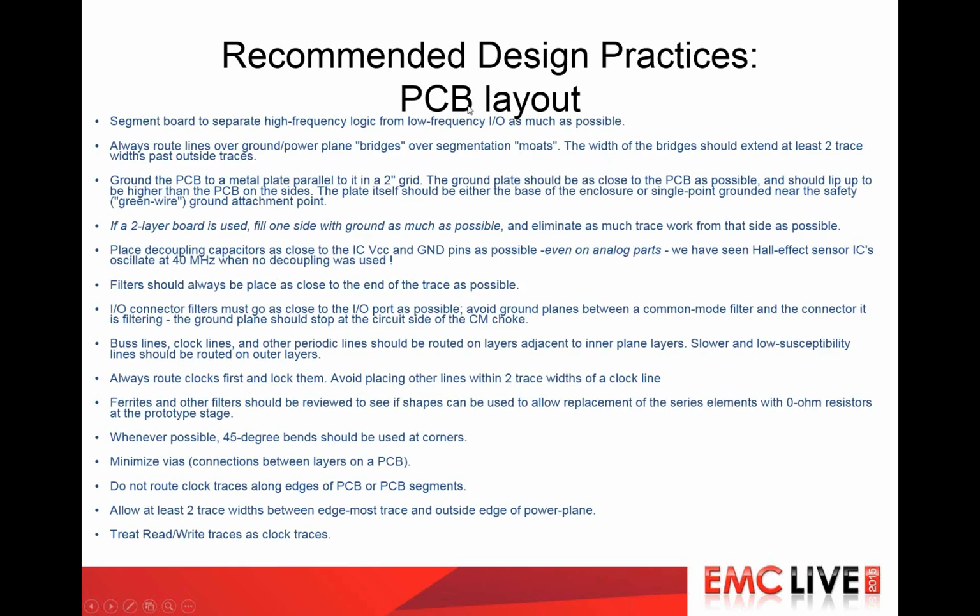Next one talks about PC board layout, and again you can see there's a lot of good information in there. Talks about filtering, how filters should be placed. Do not route clock traces next to the edges of the PC boards. So a lot of good input on that.